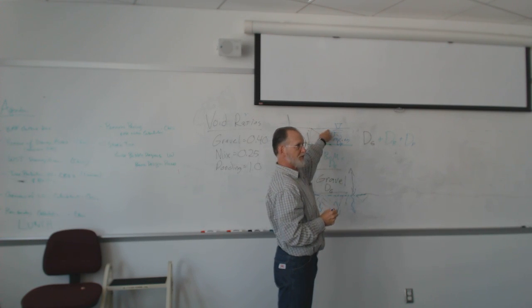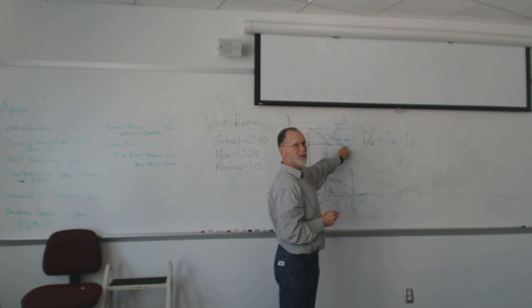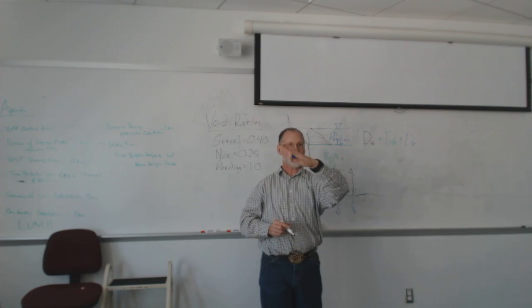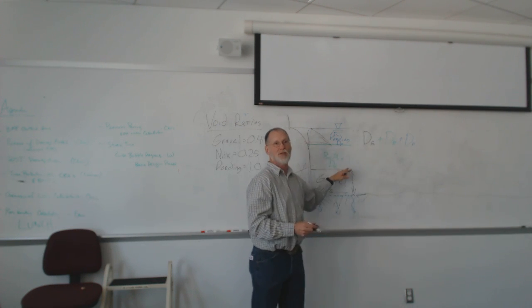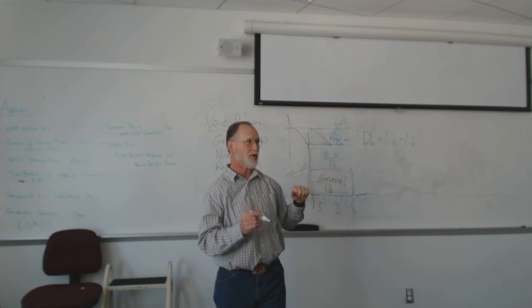So when I want 6 inches of ponding depth, all these surfaces are dead flat across the entire site. Doesn't matter if the site is sloping, all these are still flat. You just may end up with a high side and a low side of where you have to dig it out. Water won't go uphill.